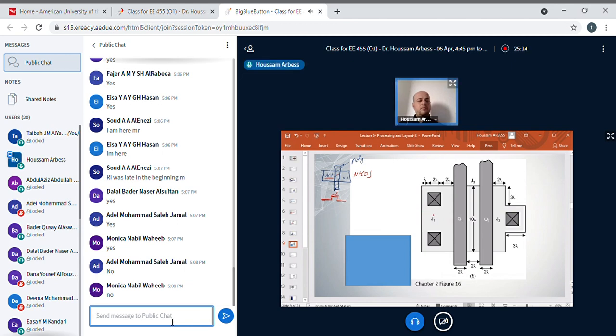Can you see here the MOSFET? Can you see here N plus, poly, N plus? Let me help you. This white gray here is N plus. These squares here are contacts. Then the two dark gray ones here are polysilicon. Now, can you see MOSFETs in the layout here?